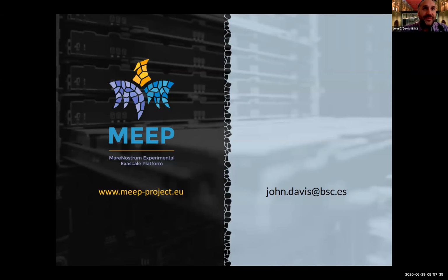The platform that we're looking at is using 8 of these FPGAs connected on what Open Compute calls a universal baseboard. It has full connectivity between the FPGAs. Within the FPGAs, they have the normal types of things, DSPs, block RAMs, that kind of stuff. They also have connectivity to HBM and have an HBM stack.